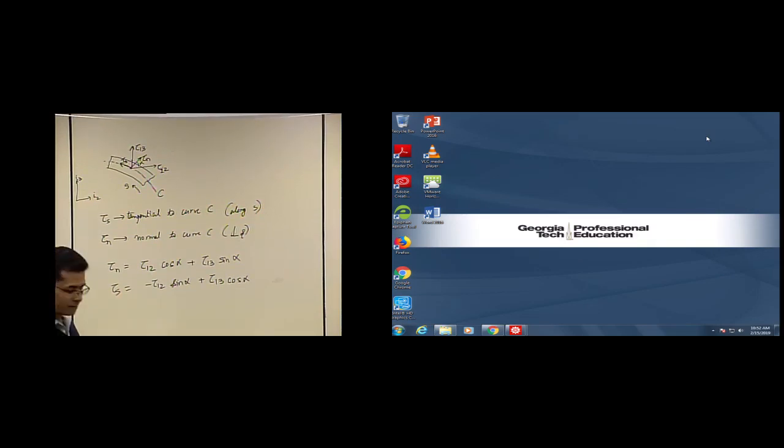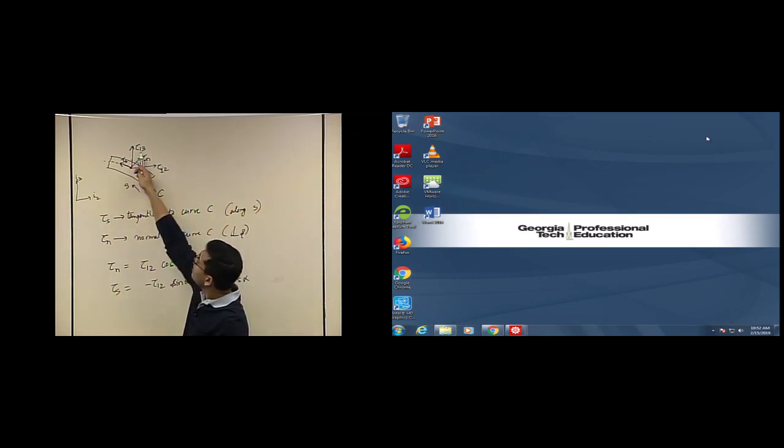I have a question. Yes. Why is tau 1 3 along the I3 axis? Isn't that just sigma 3 or no? Like, why is tau 1 3 along the I3 axis and tau 1 2 along the I2 axis? So these are the shear stresses, and the way we define them is that they are normal to 1 and they are in the direction of 3.